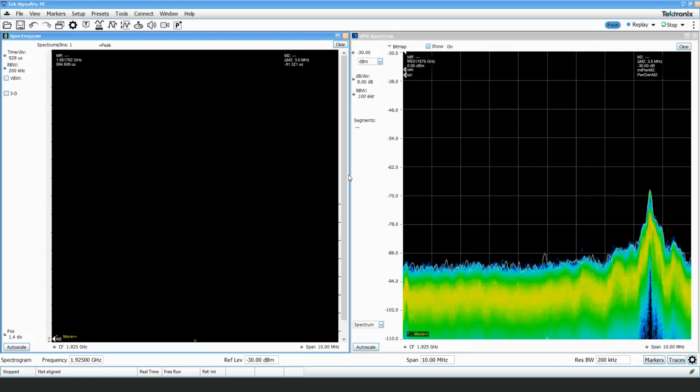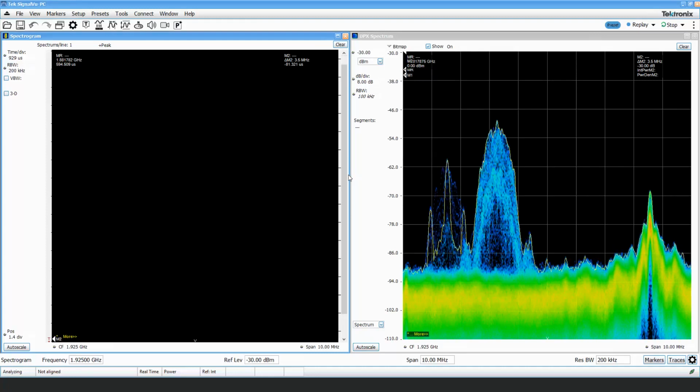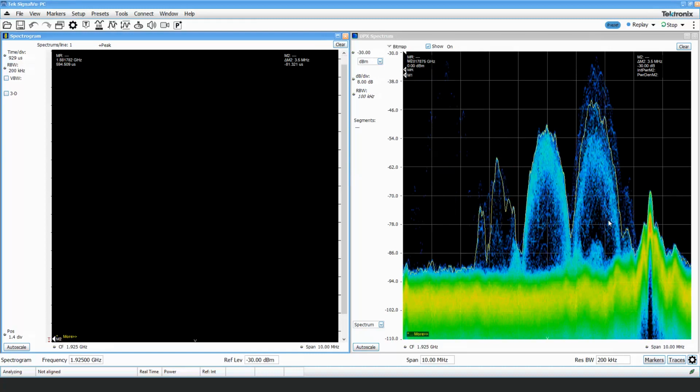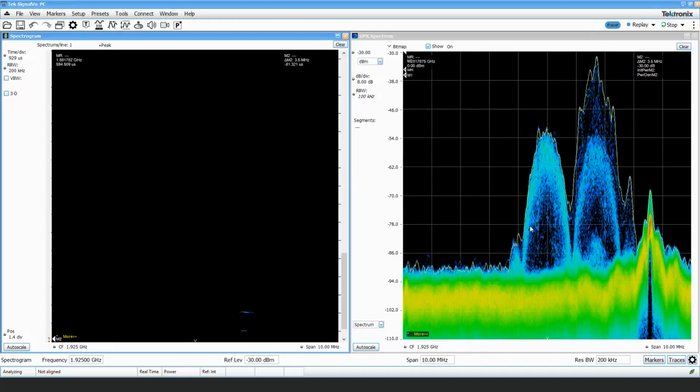And I'm going to turn one body pack on, another body pack, and then two remote or stationary systems. We start to see them come on, and all these DECT channels start to come on, and we see them hop around. As they turn on, they communicate with each other, and it looks like the two of them decided to share channels of the 5 DECT channels.